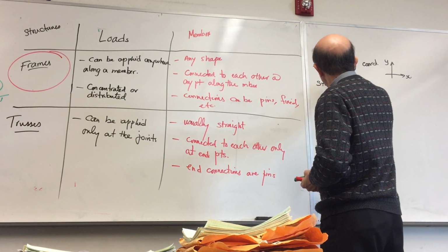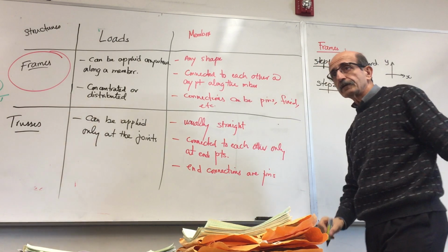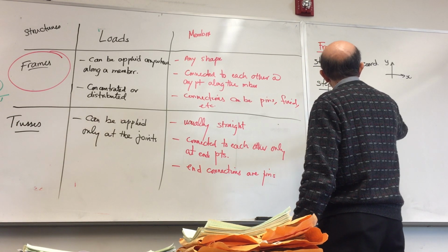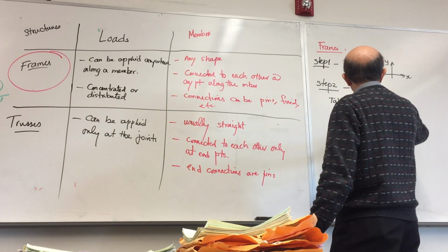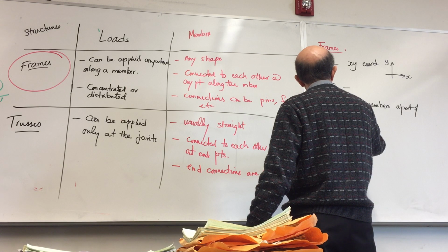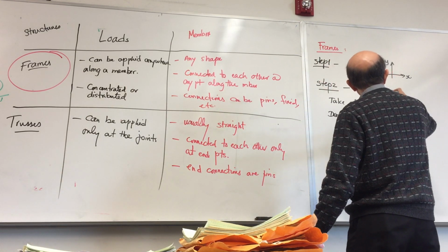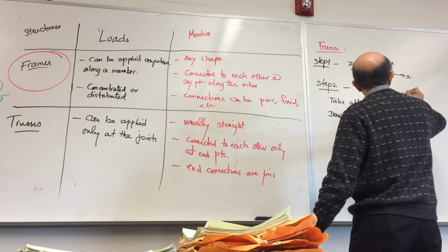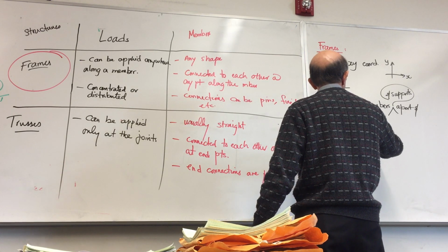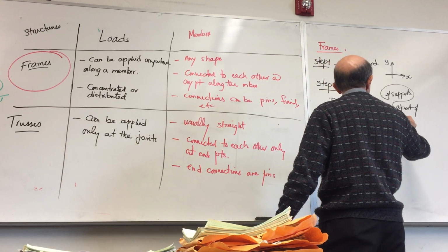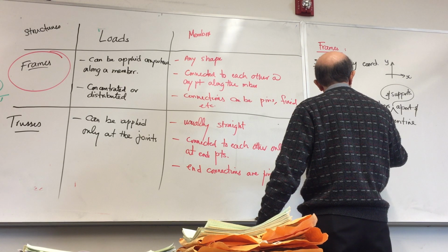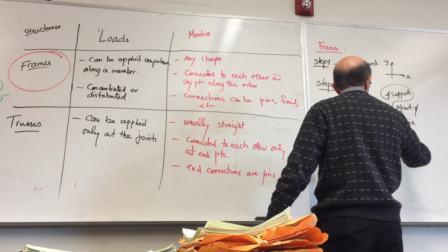Step number 2, you do this, okay? You will take all members apart and draw members and supports, okay? And draw free body diagram of the entire structure and each member.